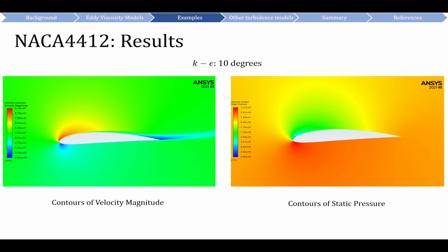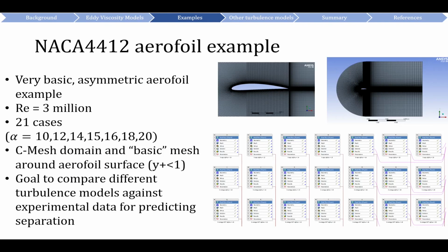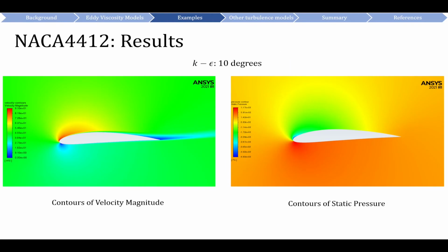After I first ran the study, here's another good check: you should always look at some very basic flow parameters before continuing into a big case study using CFD. What I mean is, before I ran all 21 of these case studies, I took this first model, looked at the flow field, and made sure all the parameters were behaving as I would expect.